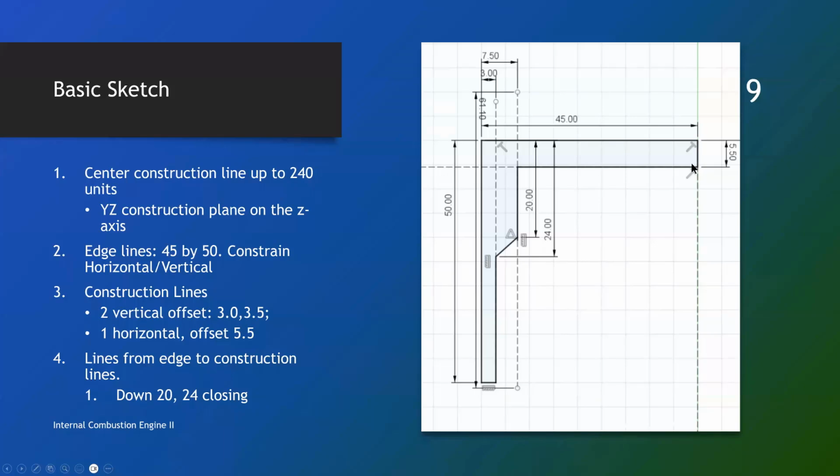So you just join this point to this point with a line, then move here with a line and constrain it to be horizontal, constrain this to be vertical, make this vertical, join it here without dimensioning at first, and just go and complete the circuit. Once the circuit is completed and it's a closed circuit, it will show you a blue color.